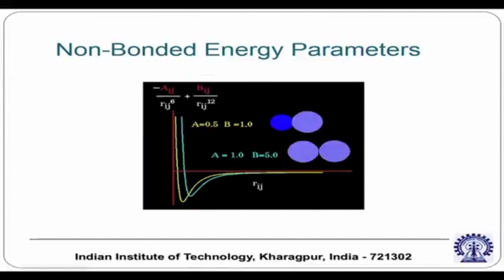For the non-bonded energy parameters, just to give you a visual appeal of how the Lennard-Jones potential will vary if you vary the parameters, and these parameters are very important. You can play with these parameters to mimic hydrophobicity and the wettability of the substrate. If you alter the parameters, different wettabilities of the substrate can be represented. So the physics of the wettability of the substrate can be translated to the molecular model by tuning the Lennard-Jones parameters.